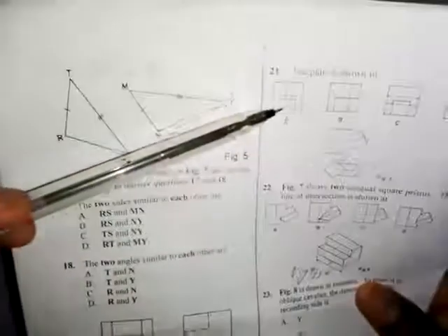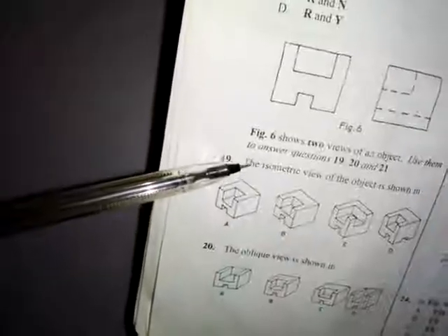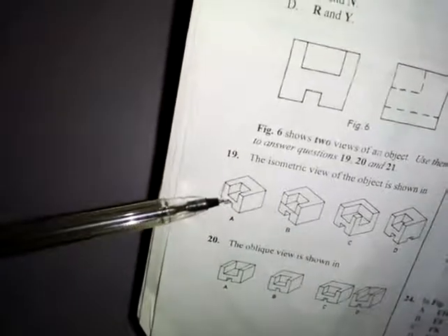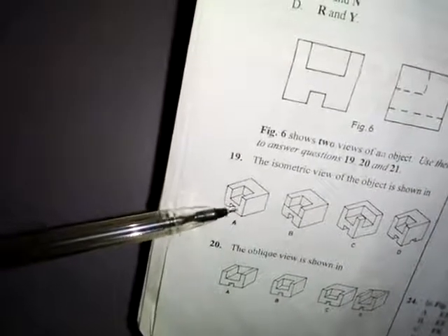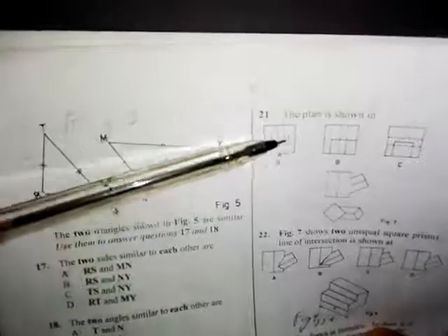And these two lines that are hidden, if I'm looking at this object from the top, these two points, this point and this point, will be hidden from me. So that is why we have this line hidden and this line shown hidden. We are shown short dashes lines. So we use short dashes lines to represent the hidden detail of the object. So option A is the correct answer.